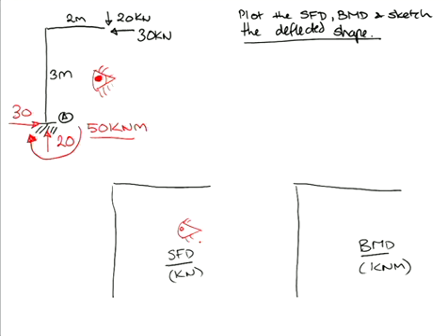If I push down here, you can see the top is in tension and the right is in tension. So my bending moment will be up above and it will be on the outside. So the value of the bending moment here will equal the same as the horizontal value of moment. And I said you can imagine that we flatten this out. So whatever moment you get here is the same as the moment you get here. Whatever moment you get in there is the same as the moment there.